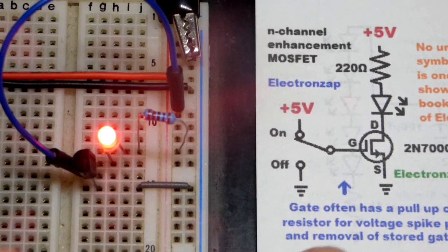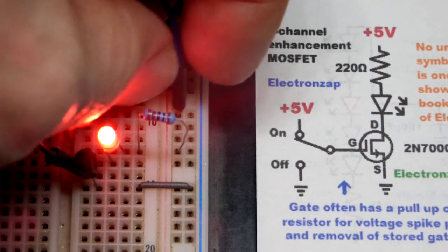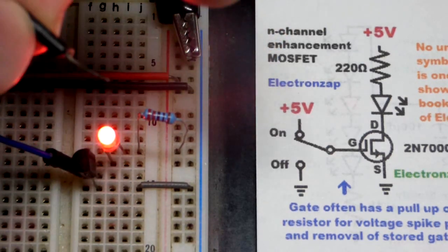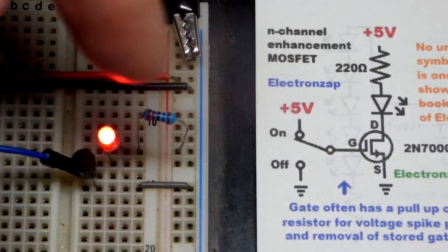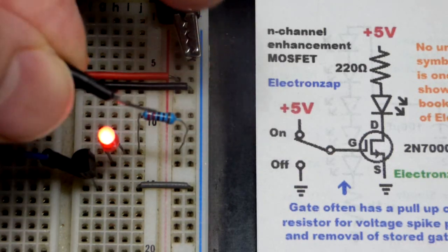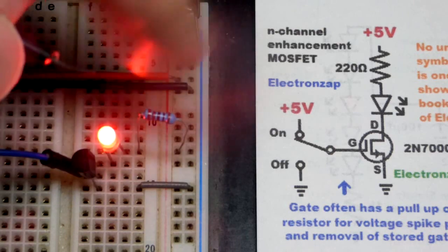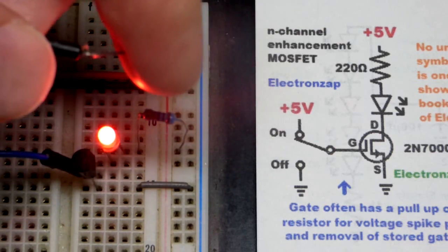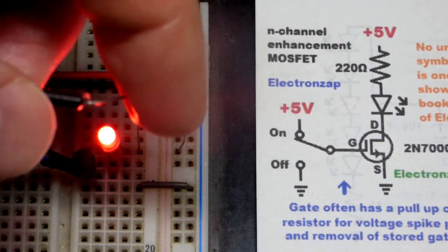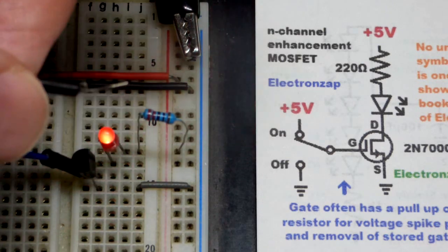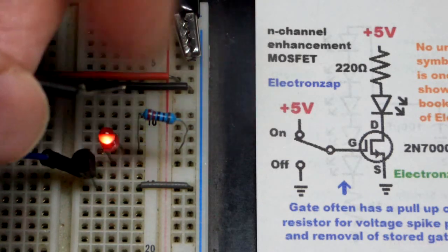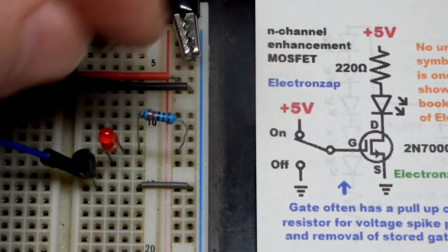So I put a little note here that you might see a pull up or pull down resistor, which is actually a really good idea. I'm going to show you why. When I pluck this, who knows what's going to happen there. It stayed on. That's because the gate builds up a charge. But there you can see it's changing, and it will change depending on how I touch it. And right now it's probably turning on and off rapidly 60 times a second right there. And it could be on, off, fully, or just some middle ground region.